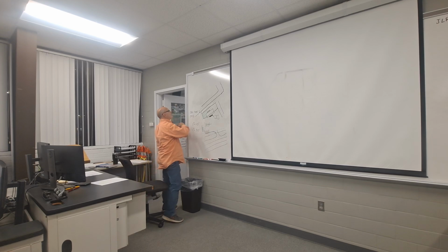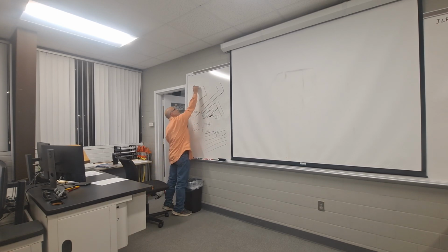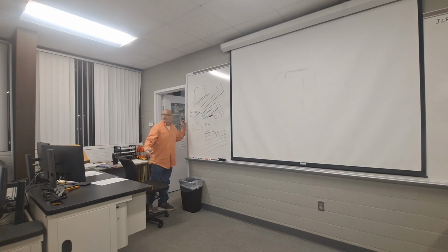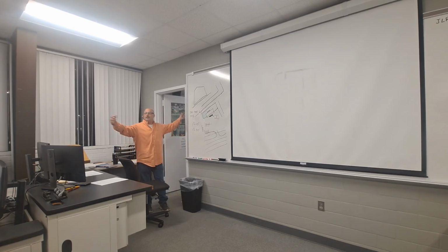So your property, from memory, is shaped something like this. Your road is down here on the south side of that property. Now, if you offset your road out, just remember to extend those lines. What I usually do is I click on it, and I click on that midpoint right there, and I go to scale 1.5, just to make it longer.